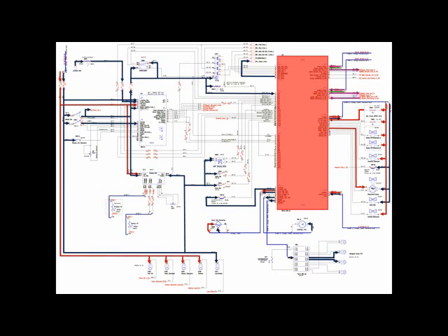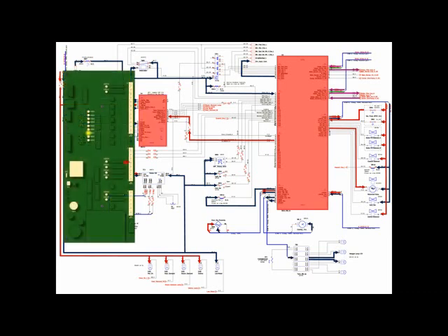The MV signal is lost at the relay board when the high temp limit stops feeding the module. The boiler heat output is lost, and the new signal from the limit indicating boiler over temp is passed to the logic board from J2 pin 4. At the logic board, it enters at J4 pin 5 and triggers LED 7.